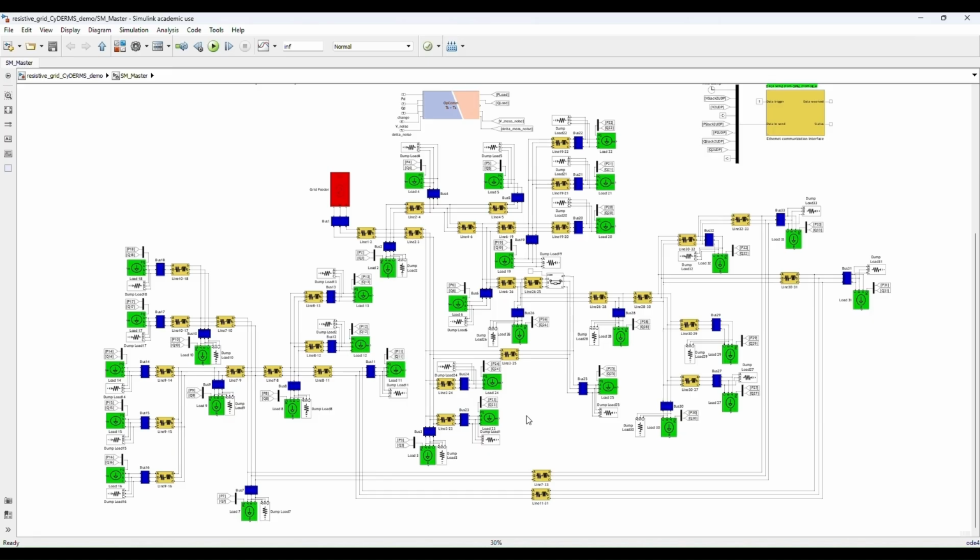In this demonstration, a modified IEEE 33 bus power network is used to showcase the performance of the reconstruction algorithm. An OP5700 real-time box simulator is used to simulate the test system in real time. We are using the eMEGAsim platform of RT-LAB for the simulation. The schematic of the RT-LAB model is shown in this window here.